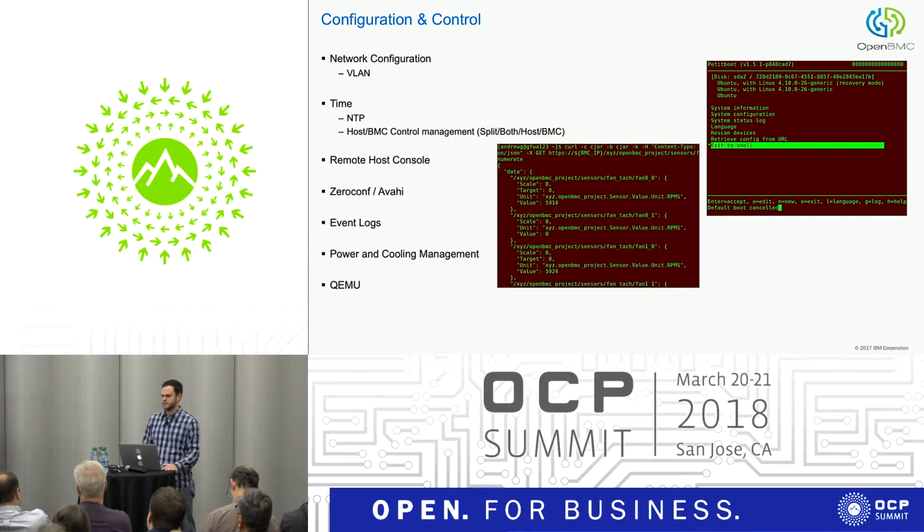And a part of that design was, you know, there's a target that says this is what you start to power on your system. But then obviously it's going to be very different from system to system and the things you're working on. And so one of the key pieces is within the bitbake recipes and layers, that's where you put in your custom ability to say this is how you really power on the system. And that's what you see in kind of the power targeting. So there's a basic infrastructure for, this is how you power on, this is how you power off, this is the chassis power on, this is the host target to start the system. And then you as a user come in and fill those in if the defaults aren't what you need.